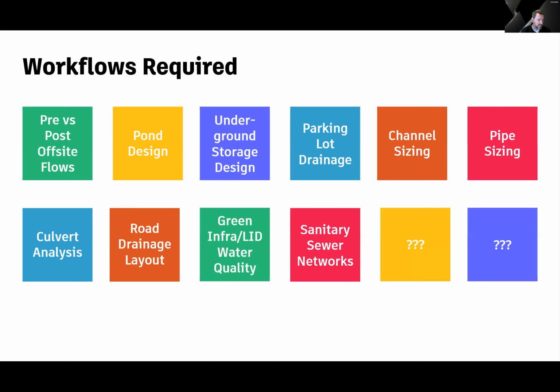I think that would need to be a part of this, but what we want to do is route the storm through them and see what impact that has on the downstream flows, and ultimately at your outfall. Are you reducing, or at least not exceeding, your downstream flows at the outfalls? I'm not sure those tools really do that.